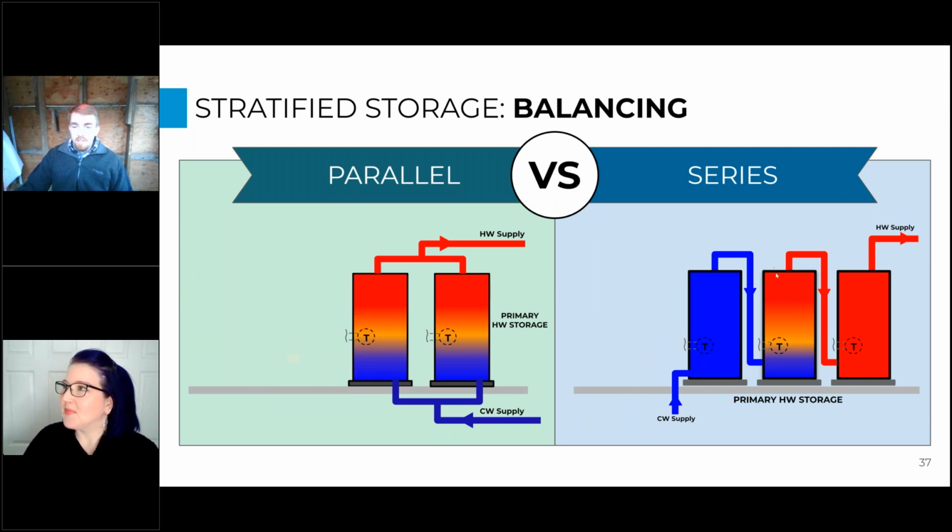That's a great question. Yeah, so I'll get rid of the heat pumps for now. And so imagine all of these tanks are charged right now. We'll talk about flows to the building. All of these tanks are charged. Now you have hot, hot, hot, and you can see the top of the first tank is plumbed to the bottom of the second tank, and so on and so forth from the second to the third. So you can imagine these as one really tall storage tank, right? The top of this tank is connected to the bottom of this tank. So as we discharge these tanks, the cold water comes into the bottom of this tank series, we'll call it, and then it just keeps on working its way as this hot water is drawn out from the top of the tank. But when we're recharging it with the heat pumps, the opposite happens.